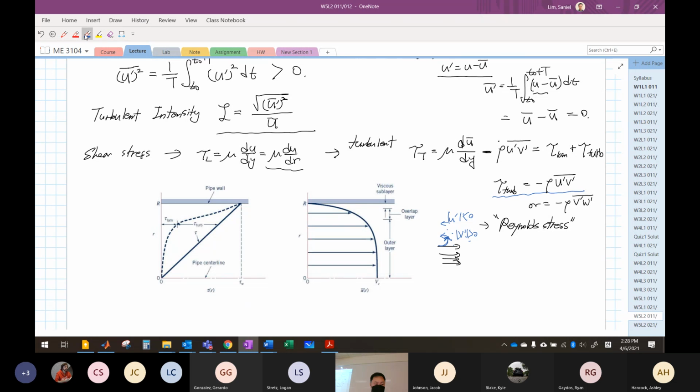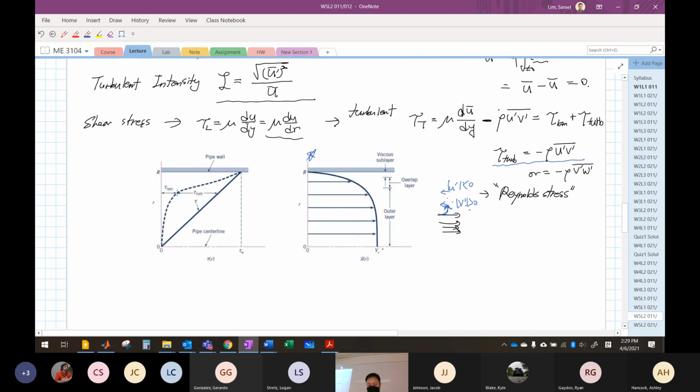Then in the figure here, you can see in the turbulent flow, let's take a look at the velocity profile first. You've already seen this type of velocity profile, an axisymmetric one. So if I have a pipe like that, it's going to be like this. Of course, if we had a smaller pitot-static tube, we could measure this shape near the wall. You couldn't find it, but we have a little bit of a boundary layer there.